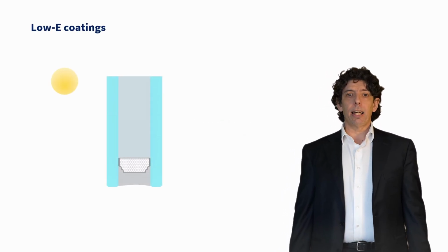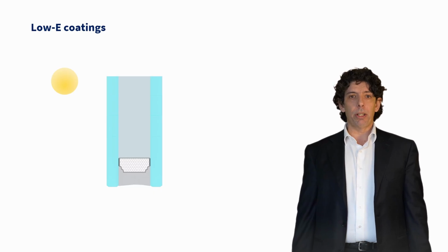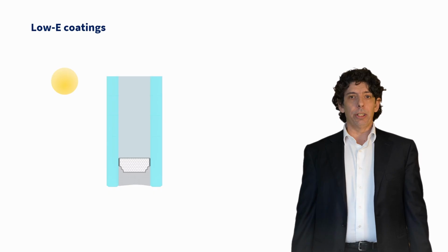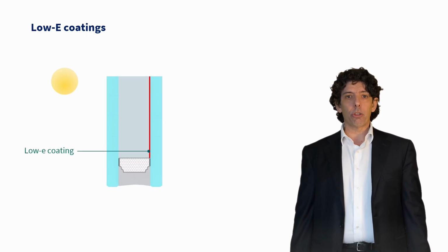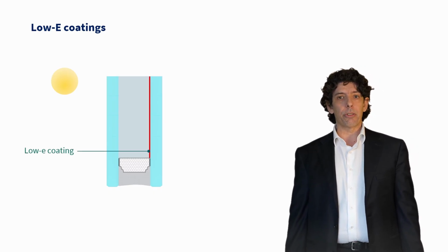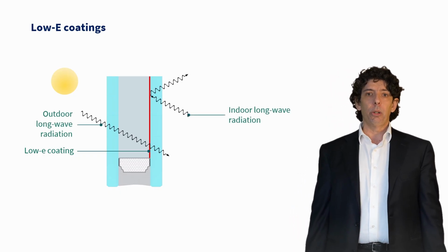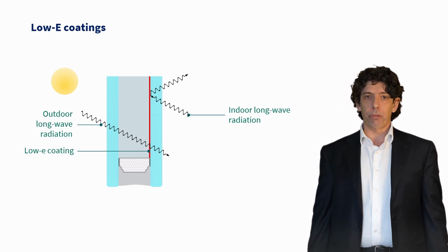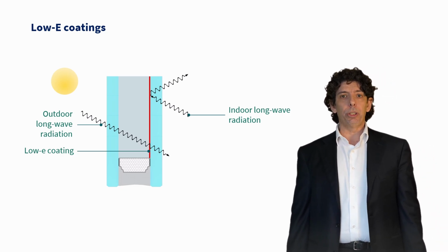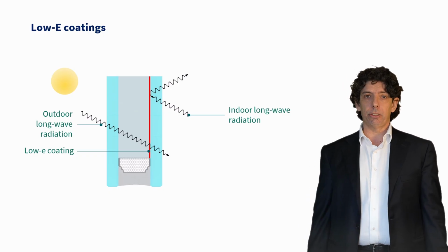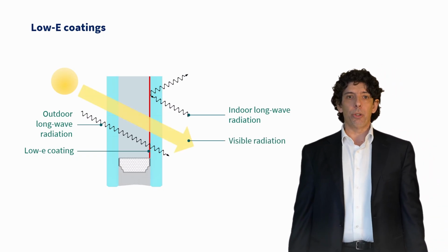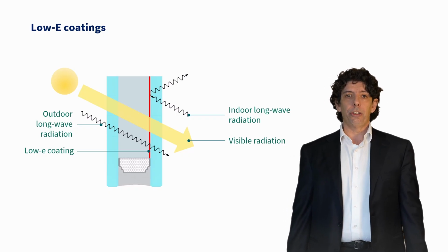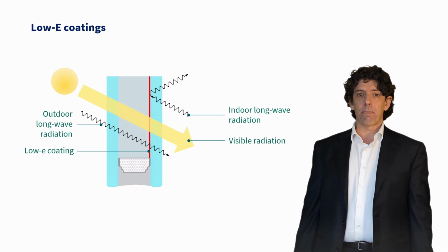Using coated glasses allows to improve the management of the visible and thermal radiation. The low-E coated glass located on the inner glass pane can reflect most of the indoor long wavelength thermal radiations, allowing to keep the indoor heat within the thermal zone, reaching excellent thermal insulation and high occupants comfort. Usually, they come with the qualities of excellent light transmission and low reflection, which allows maximum light penetration through the glass while providing low thermal transmittance and good clarity.